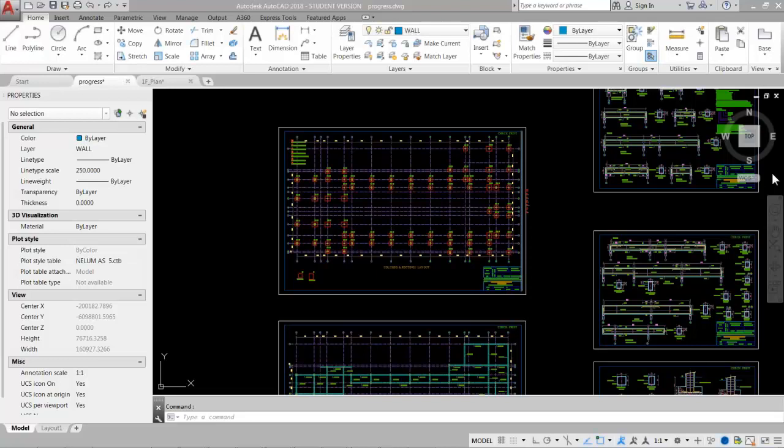Right, after performing the design, we can look at the strength check result. Okay, and here we can see the status of our entire structure. It's very colorful, but the reason for this colorfulness is the different demand capacity ratios that have been achieved. There are many that require a check, meaning the ratio is very low and we need to do more optimization of those members. The blue colors that we can see are passing with a good ratio.